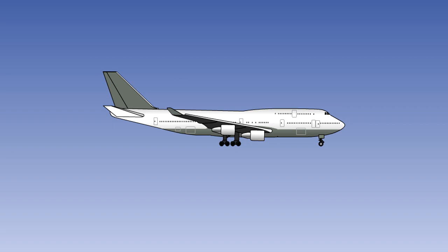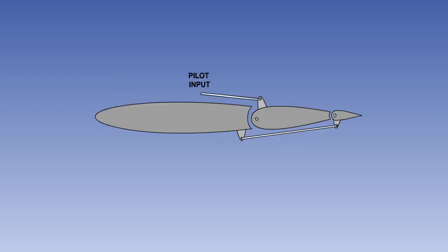Modern large aircraft have flight control systems operated by hydraulic power. However, smaller aircraft will have a mechanical system where the pilot provides the motive force. Having moved the control surface, he will have to maintain a force on the control to oppose the aerodynamic force, which will be attempting to reverse the operation and return the surface to the neutral position. For this reason, manually operated flight controls are known as reversible controls.